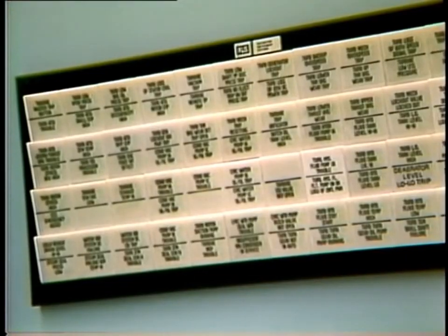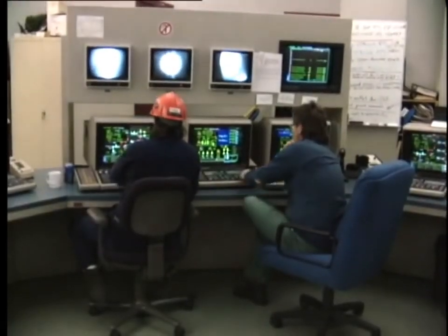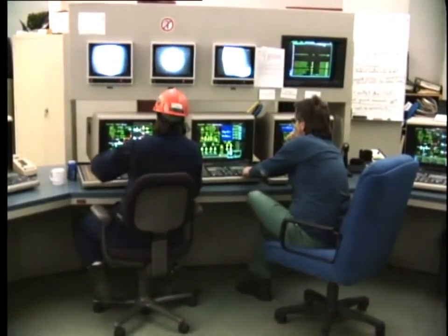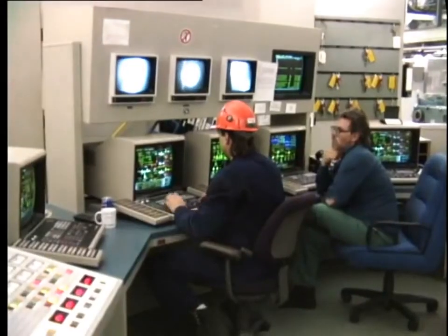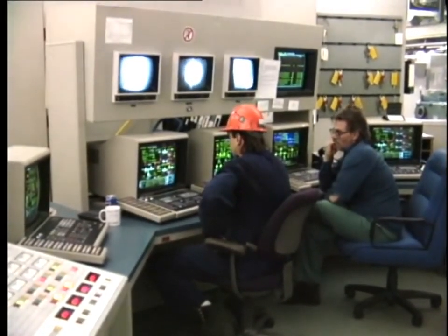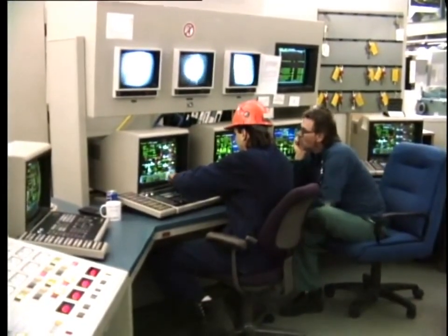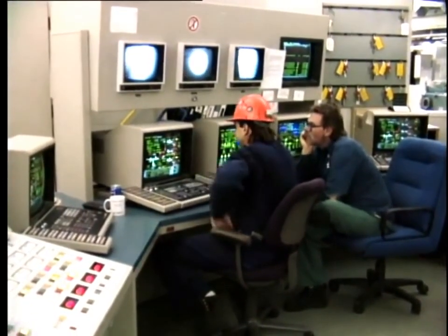The annunciator panel, usually located above, provides indication of any alarm conditions. In newer plant installations, and in fact in many converted plants, digital control systems are employed, and in this case, the operator works at a console with 3 or 4 CRTs, providing indications, alarms, and the means for remote operation.